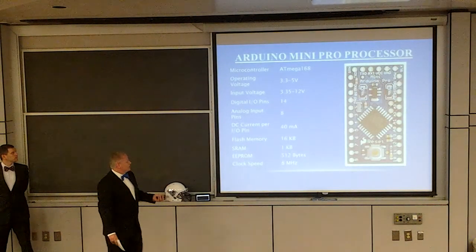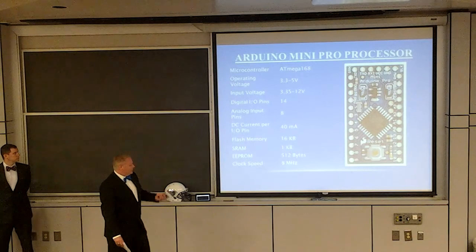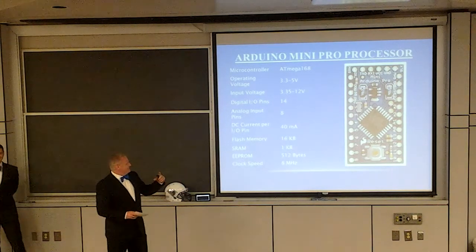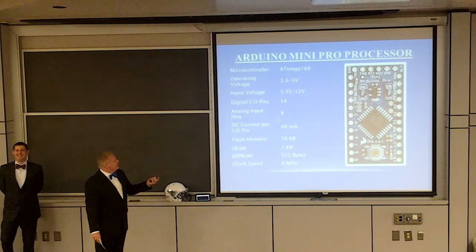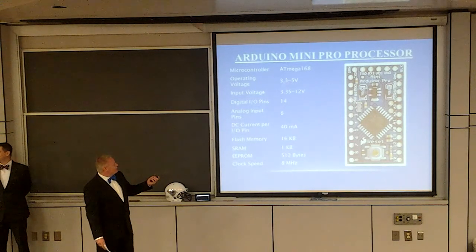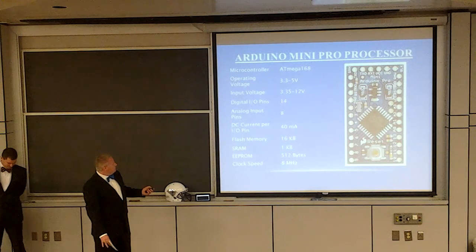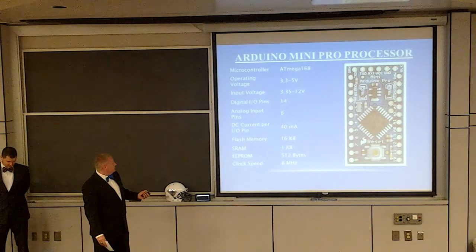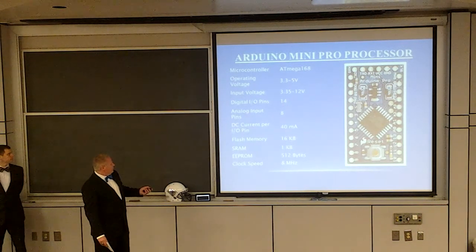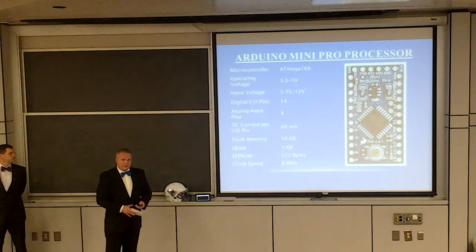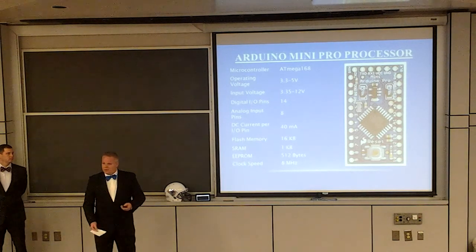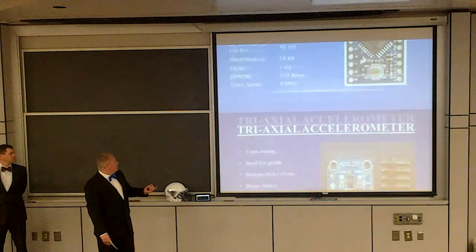The Arduino processor is actually huge here, but it's only about an inch high, 2 inches. It only takes 3.3 to 5 volts to operate, and it has 14 digital outputs, 8 analog, and it only runs on 40 milliamps of power, which is pretty low. We can sustain that with battery power.